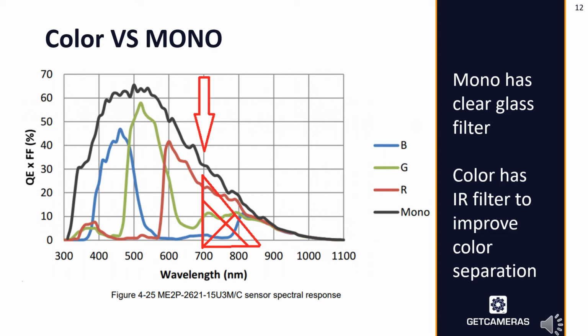You can see the red, green, and blue colors there. Basically, a monochrome camera is capturing the visible light, like RGB, but it does also go further and capture the near-infrared light. A monochrome camera has a clear glass filter installed simply for dust protection, let's say, from the sensor. An RGB color camera does capture the 3 separate colors, of course, and it does have a near-infrared filter installed. This means that with a color camera you can't see near-infrared light.